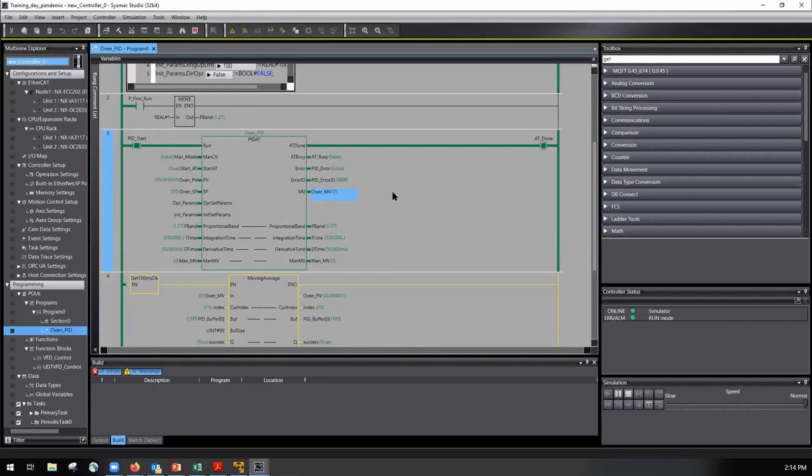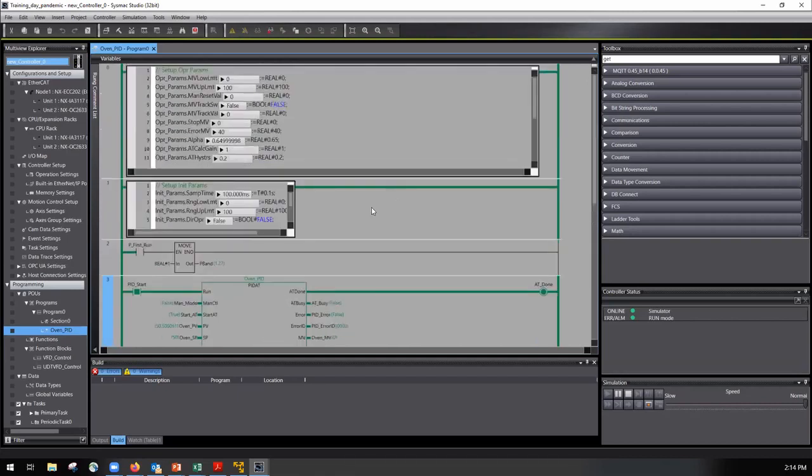You get the idea. So part of tuning is finding a calculation gain parameter that works if you're going with the auto tuning method. So if you write down a note about anything today, make that the note. It can save you a lot of time.